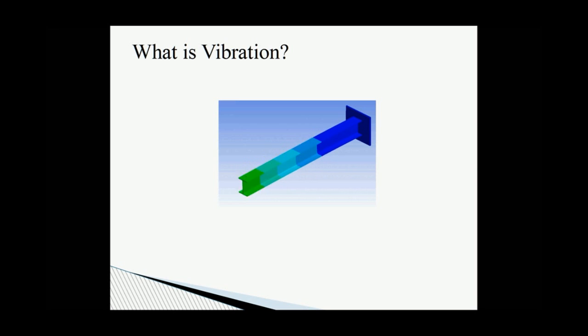Now, you'll be able to use this information, along with collected field data from, let's say, a car engine, which inputs vibration into your component or structure on a car, or from a rocket engine, which inputs vibration into your system or component mounted on your rocket. You'll be able to take that data and compare it to the modes, look at the frequencies at which your modes occur, and look at the frequencies and amplitudes of the vibration source, the force that's causing your vibration, which could be an engine or wind passing across a tower or building. You'll be able to determine whether or not those modes are in the operating range of your system, and whether or not your structure will be damaged as a result of the operational vibrations that it will be exposed to.